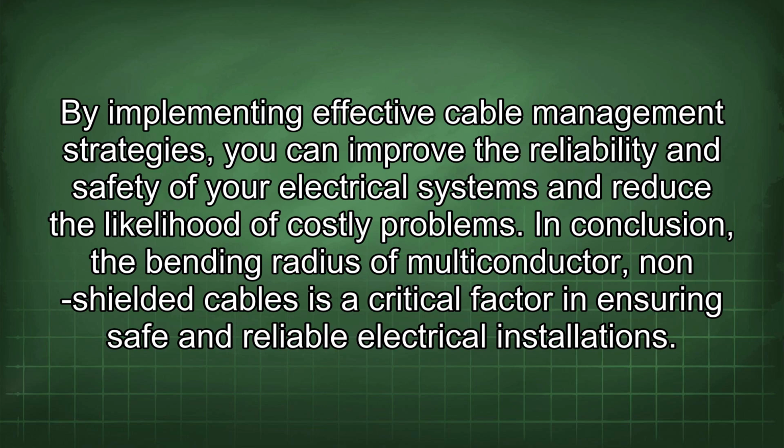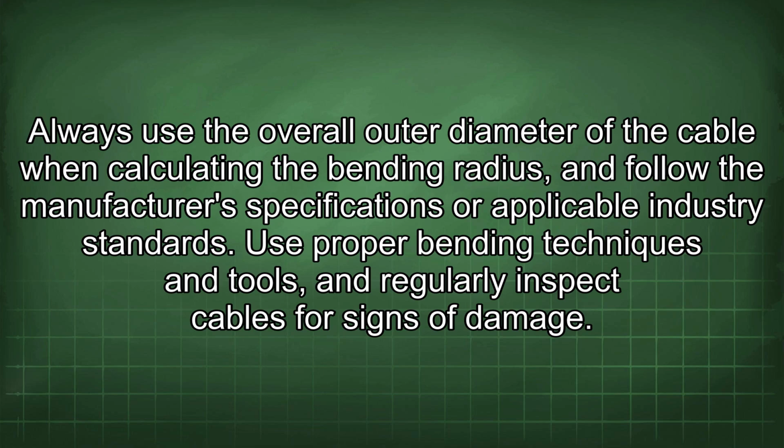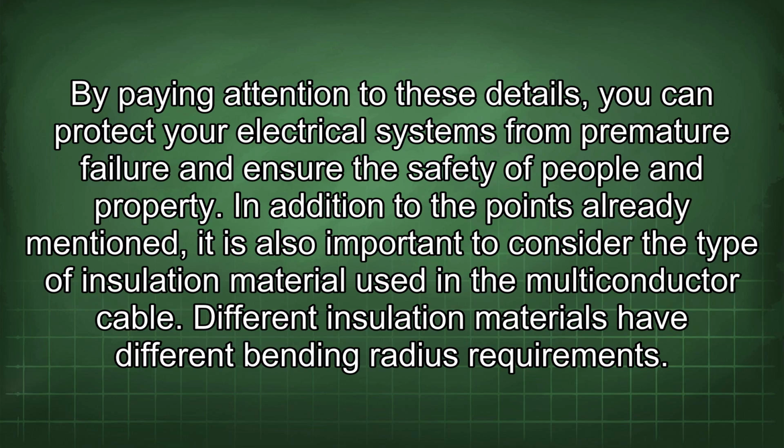In conclusion, the bending radius of multiconductor, non-shielded cables is a critical factor in ensuring safe and reliable electrical installations. Always use the overall outer diameter of the cable when calculating the bending radius, and follow the manufacturer's specifications or applicable industry standards. Use proper bending techniques and tools, and regularly inspect cables for signs of damage. By paying attention to these details, you can protect your electrical systems from premature failure and ensure the safety of people and property.